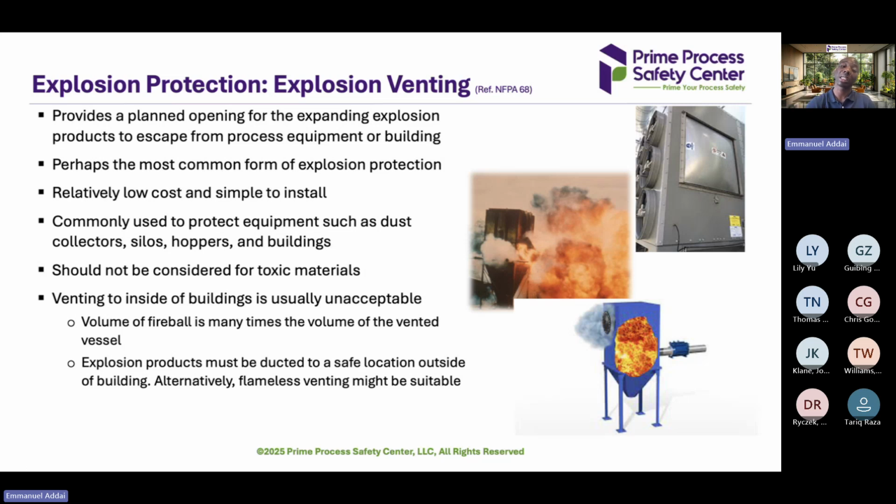But if you are not inerting the system, there are the filters, and normally when you pulse, a dust cloud is generated in the immediate layer of the filters. And as I mentioned, the secondary basis of safety is ignition source. You can never eliminate all ignition sources, so the only things always present are the concentration and an energetic ignition source. So every dust collector per the standard needs to be protected. The protection is having explosion relief.